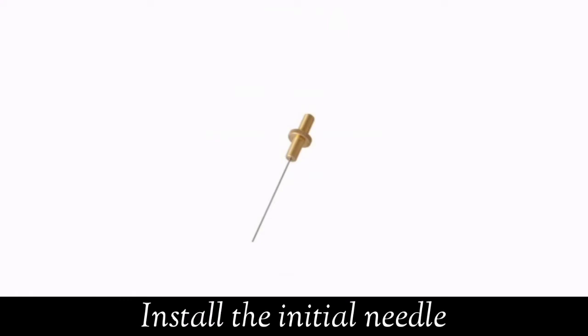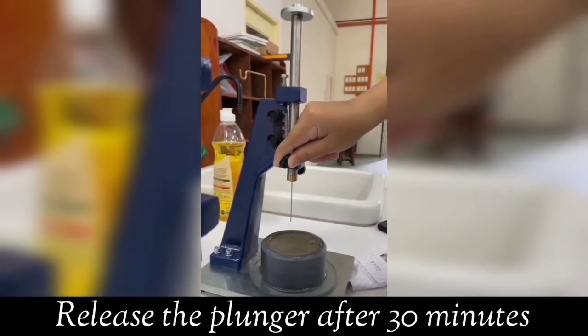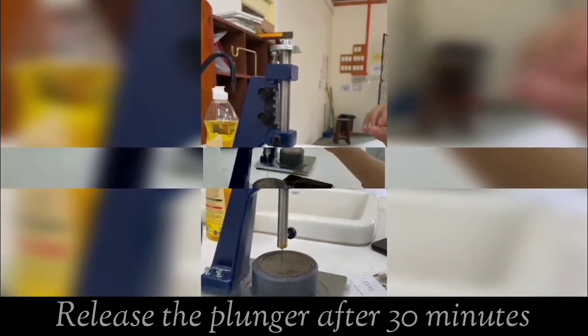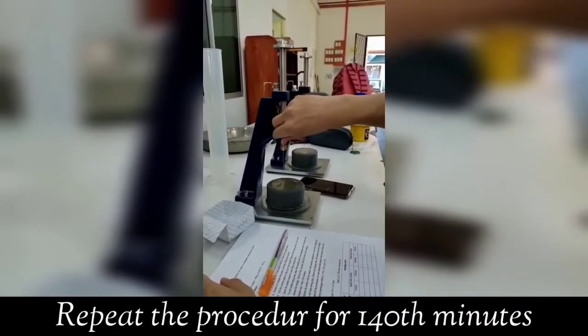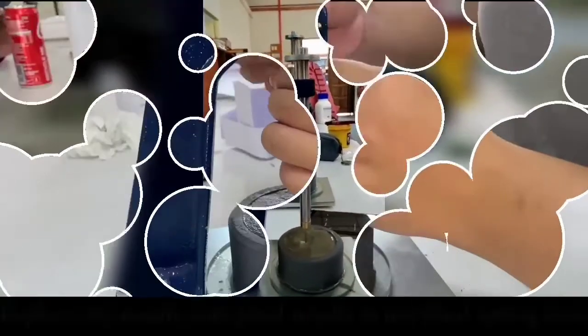This is well known as the initial needle. Install this initial needle to test the initial setting time. The mold is placed at the VICAT apparatus after 30 minutes and the plunger was released. Wait for 3 seconds and note down the reading. Repeat the procedure after 110 minutes, which is the 140th minute.